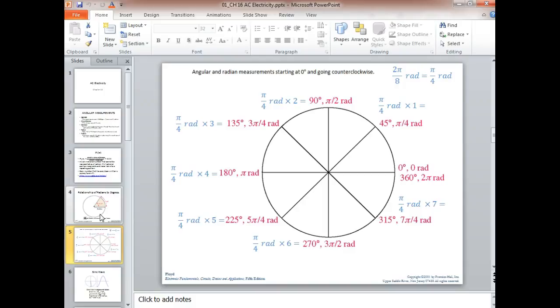But everybody doesn't have to do that. So what I'm saying is, just don't take for granted that RSLogix 500 supports it, or that the PLC you're using supports it, right? You need to get the manual on the PLC and actually look at the addressing modes and see what instructions that thing actually supports.